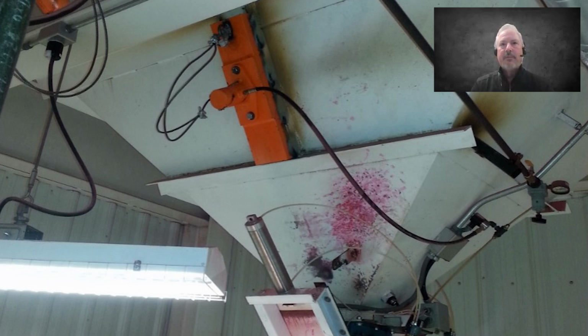Now, seed corn generally flows very freely, but it's that chemical additive of the insecticide and fungicide that they add to it. As it sits in that hopper for a period of time, that hardens. And they open that gate, nothing comes out. They have to break that loose. So we applied, as you can see in there, a pretty large piston vibrator to replace the operator from having to lean over the railing to knock loose that material.